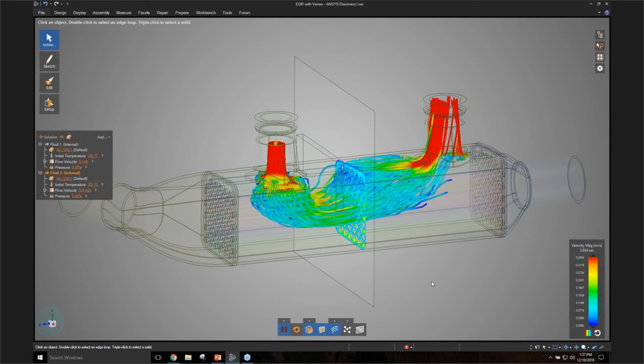Okay. I'm using a P5000 NVIDIA card, which has 16 gigabytes of dedicated video memory, which is really cool. If you can get that, that's awesome. But one level below, for example, a P4000, you have 8 gig, or one level below that is 6 gig. Those are all great types of cards you can use. Okay. If you're like a one-man consulting shop and Quadro cards are a little bit expensive, the consumer grade GeForce will also work, but of course we recommend the Quadro cards. So NVIDIA, minimum 4 gigabytes dedicated video RAM. That's what you need to worry about.